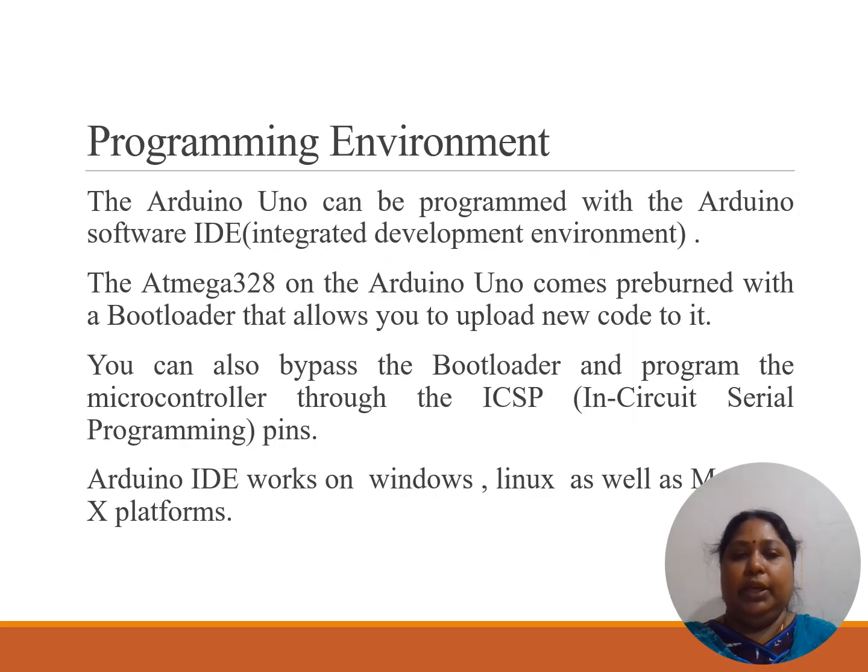Coming to the programming environment, Arduino Uno can be programmed with Arduino software, which is Arduino IDE. It uses the microcontroller named Atmega 328 and a flash memory. The Arduino Uno has 32 KB of flash memory, of which about 0.5 KB is utilized for the bootloader.